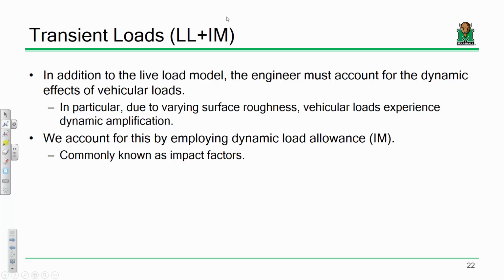It's reality. Now, if you're driving, let's say, a cement mixer or a short-haul vehicle, or a cement mixer. I said it twice because I wrote it twice on the slide. But if I drive one of those and I hit potholes, or if I encounter surface roughness on the road, what does that mean for the bridge? You all used the exact right word, you're getting what's called an impact force.